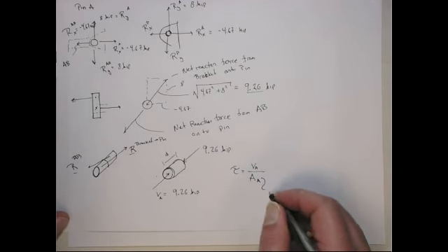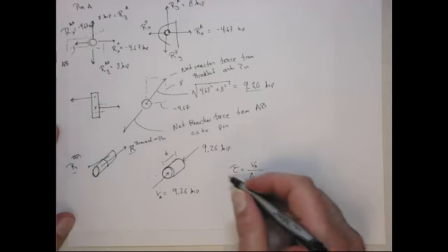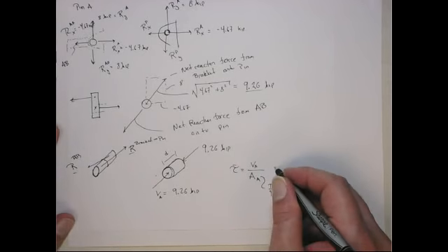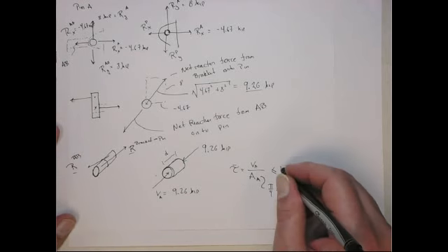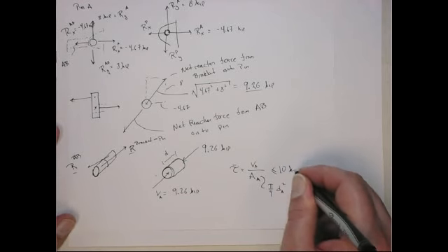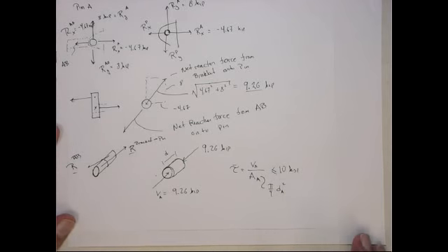So this is pi on 4 diameter of pin A squared. And we know this quantity here has to be less than or equal to the allowable, which is the 10 KSI. So we'll pick a limiting case where it's equal to and figure out the minimum area or the minimum diameter that makes this work out.